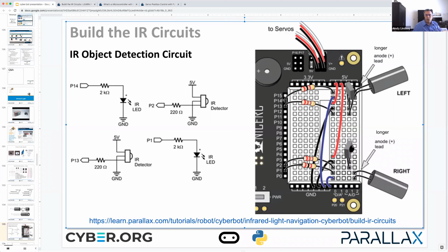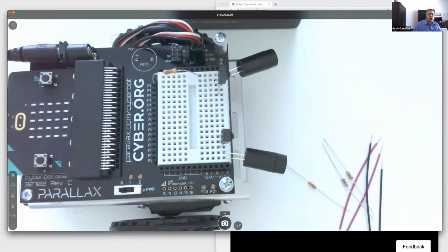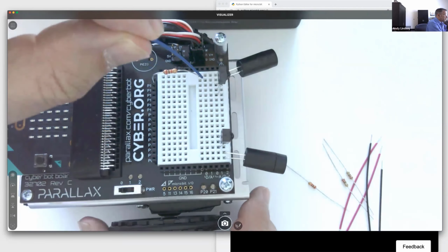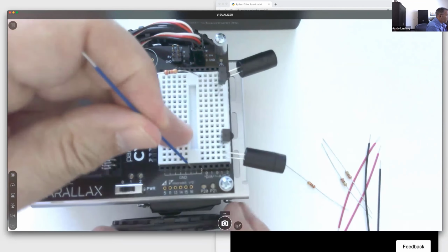it looks like we don't have enough wires for this. I'm using blue wires to connect the LEDs to ground, and I didn't see those wires in the picture. So I know you grabbed 2 black wires already, but grab 2 extra blue wires. The reason I grabbed blue wires is because in a distance sensing activity that we haven't yet published, those go to the D to A ports right here. But for now, we're just going to put them into ground right next to the D to A ports.